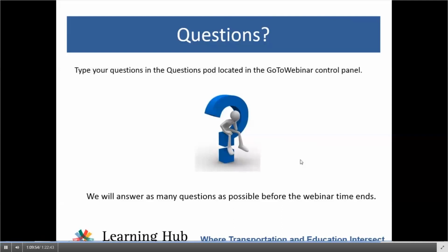Okay, that makes sense. I think for freeways, that's similar to the last question that was asked, that the computational engine won't do that for you. The method itself, there's nothing that prevents it from looking at multiple hours, but you would probably also want to consider using FreeVal at that point, or another tool that implements the HCM operations method. I would say the planning method itself would give you a good idea of how many hours you need to consider, because it'll indicate that. But then you really need to jump back into the full HCM method to figure out the real impact of all that.